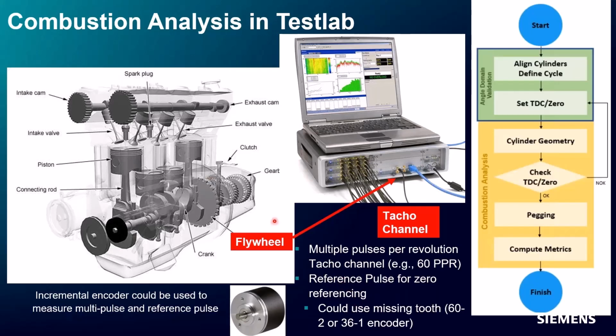Yes. And of course, we acquire data in the time domain. It's very important to have an accurate tachometer or high pulses per rev so that we can transform the data from time to angle. Yes, that's what we're going to use this for in order to do this combustion analysis. That's right, Pete, an excellent point. We will be measuring data with respect to time, but we need to convert that to angle so that we can get the pressure and the volume in terms of the angle.